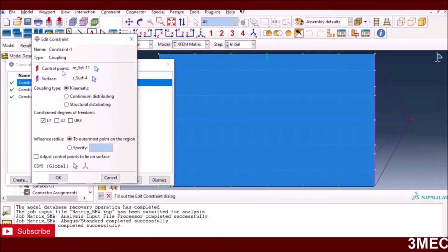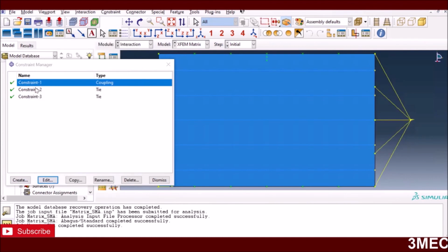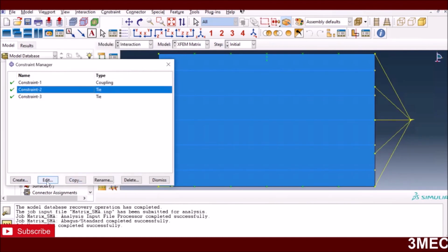So I select this surface, and then I select the control point, which is this reference point. So you see now everything on this surface is connected to this, and I'm only connecting u1 because I'm just moving in the x direction so that it can still contract when I pull it, which is the case because this surface is free. So this is again an assumption I have made, but you can decide if it's good enough for you or not.